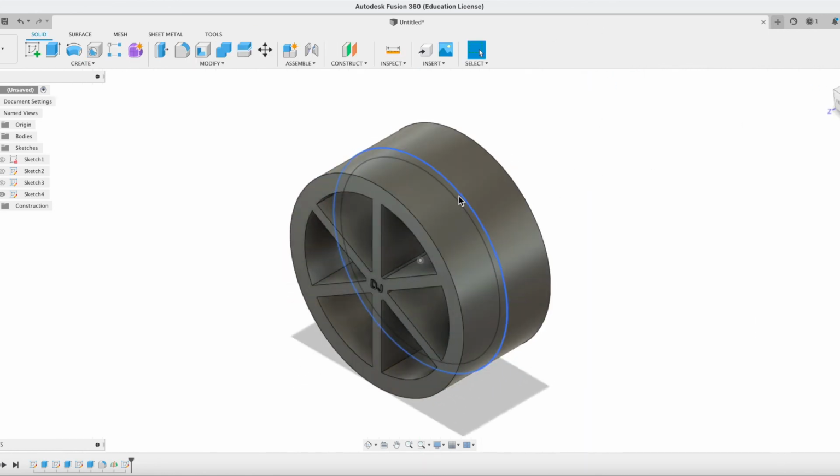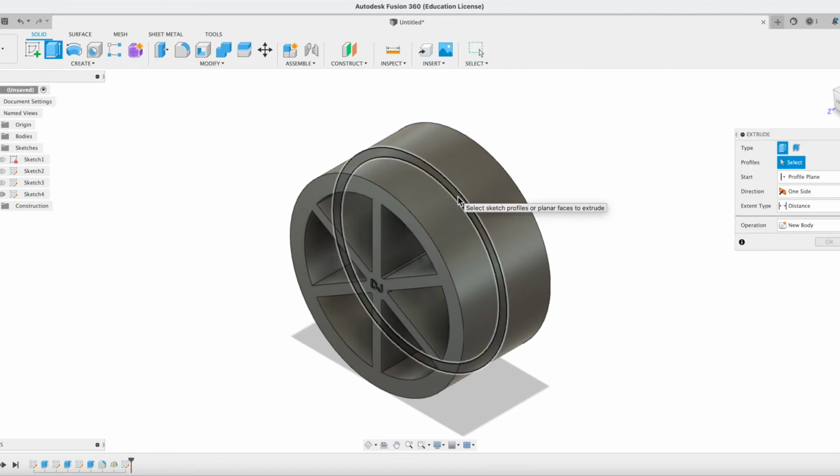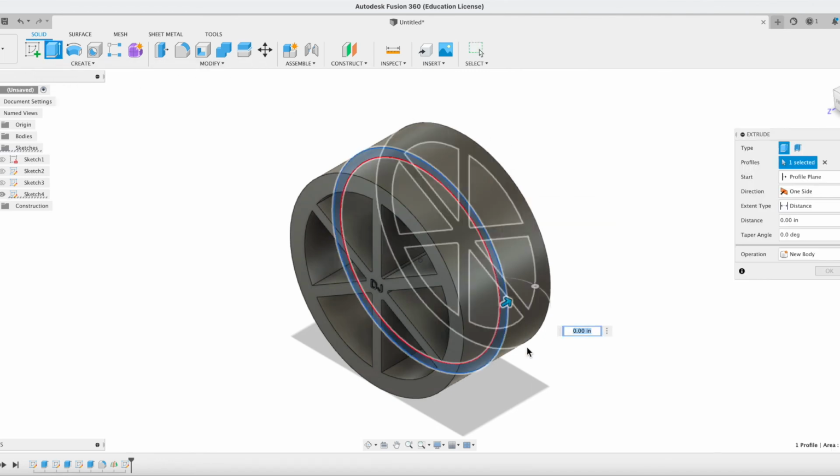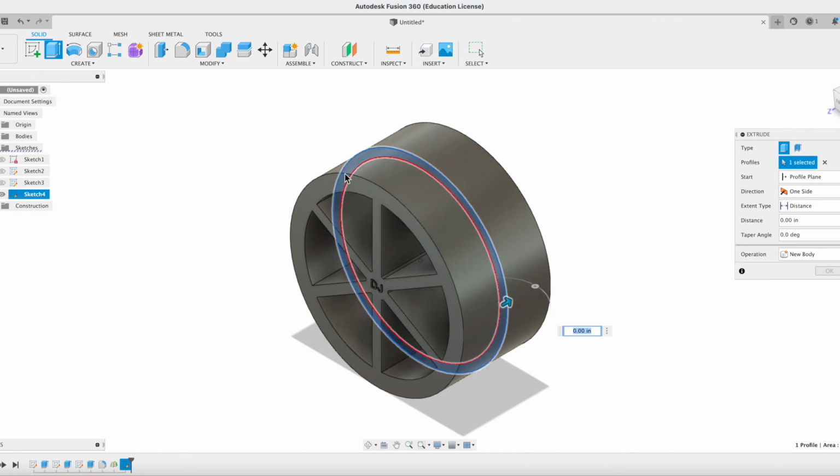You can't see it, but if you click the extrude tool, it'll let you click the sketch. If you can click the sketch, then it'll extrude it in whatever direction you want. We're gonna learn something new here too. Direction: symmetric. If everyone knows what symmetry is, it means something is the same on both sides.